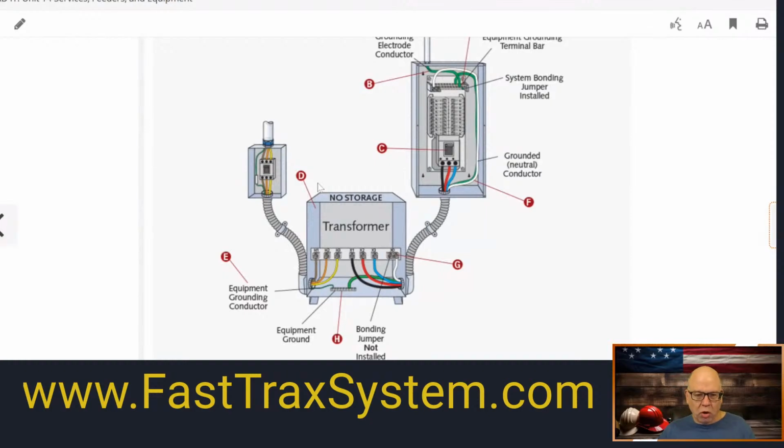You want to make sure that in the panel that you're working, you have done an adequate load calc so that you know whether this 75 kVA transformer is going to work for you. This is a 120/208, and we saw that the output device here is going to be 225, because that means this enclosure is rated 225, right? Remember we did this one earlier?